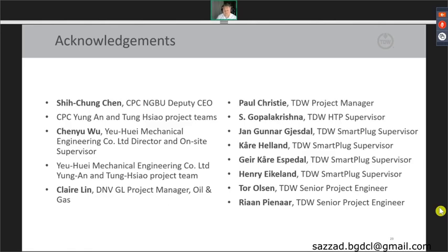The next question is from Mr. Kamrul Islam. How the chips are collected from the pipe when drilling in online system? Yeah, for hot tapping, you cannot avoid that some of the chips will actually fall into the pipeline. That cannot be avoided. The coupon will be retrieved, but the chips from the cutting, they will fall into the pipeline.